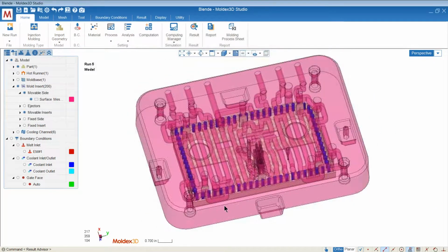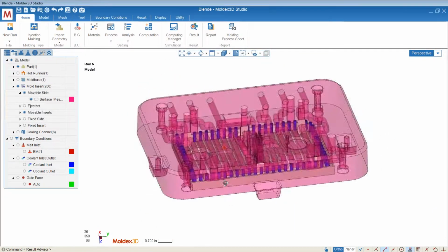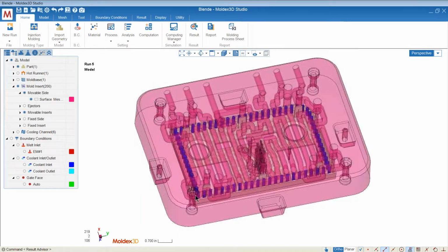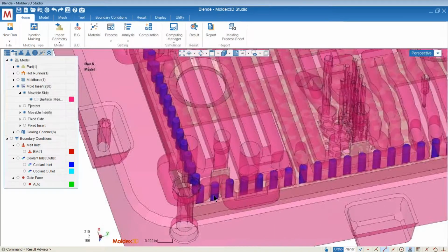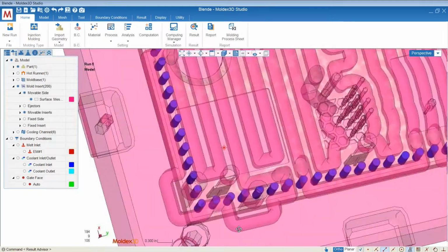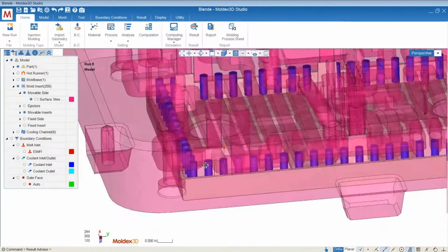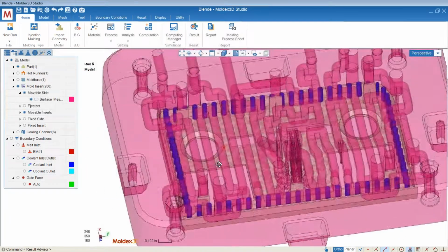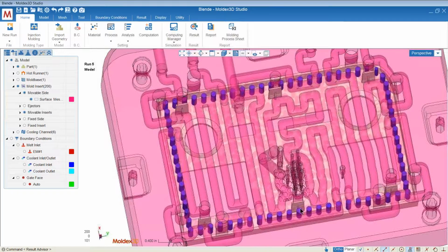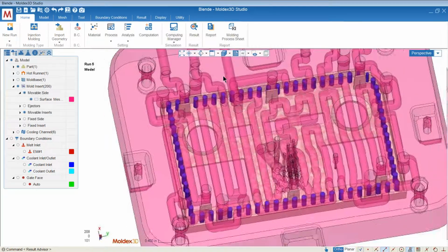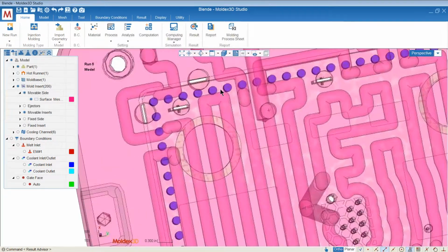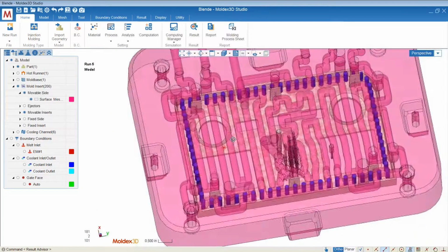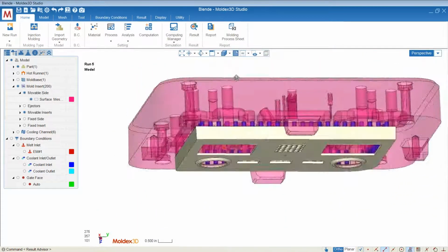Those blue markers are pure copper inserts. They have been put into this conformal cooling mold cavity to further enhance the withdrawal of the water. Yeah, some of them, as you can tell, touch the water, and the water is cooling the system, cooling these corners inside of the part very quickly.